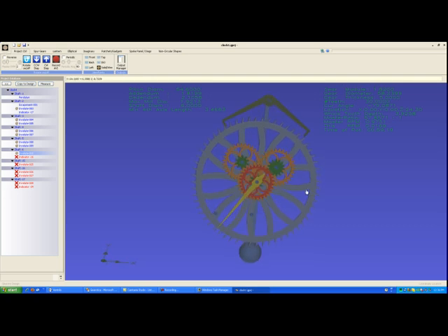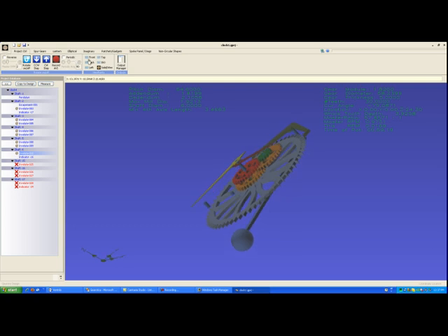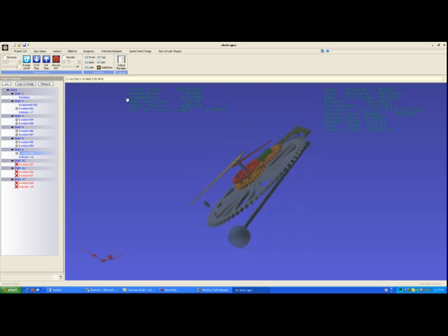So this gear now, when I select it, you'll see has a timer rotation of 59 minutes and 19 seconds. That's real close, and certainly close enough for our purposes. So we can add an indicator to that gear, and now we have our minute hand. There are many ways to attach an indicator to a gear. You'll see Gearotic Motion just shows it on the shaft. That's not really where you'd put it in this case. You want the indicator attached to that gear so that it rotates once per hour.